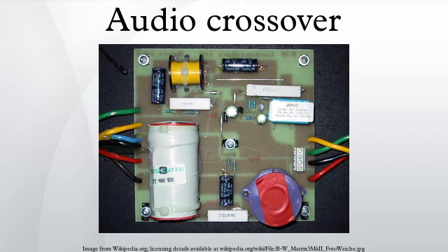All first-order filters have a Butterworth filter characteristic. First-order filters are considered by many audiophiles to be ideal for crossovers. This is because this filter type is transient perfect, meaning it passes both amplitude and phase unchanged across the range of interest. It also uses the fewest parts and has the lowest insertion loss.